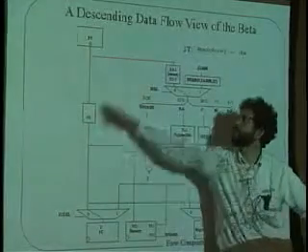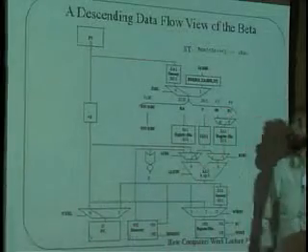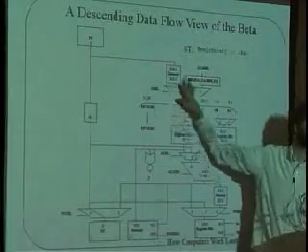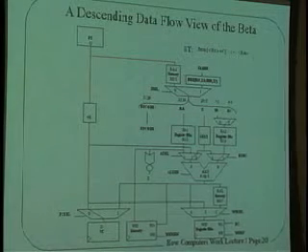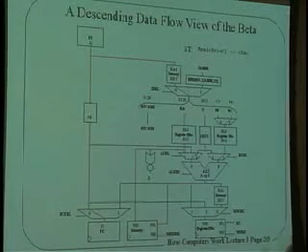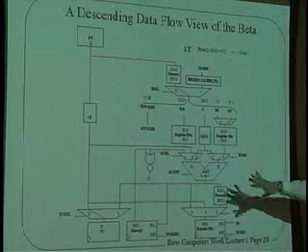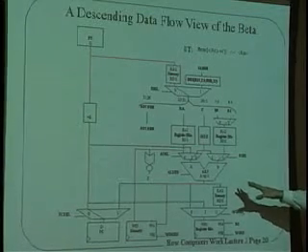Nothing has changed over here with bumping the PC by 1 to get to the next opcode. Nothing has changed up here in terms of fetching the contents of the PC to find out what instruction it is that we want to do. But this is neat because now you've, I think, seen all of the different paths being used in order to do the different types of opcodes that we have.